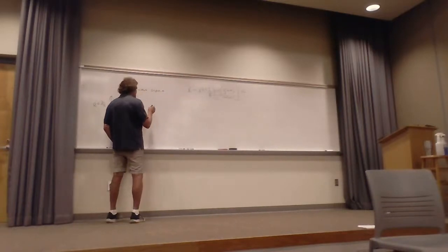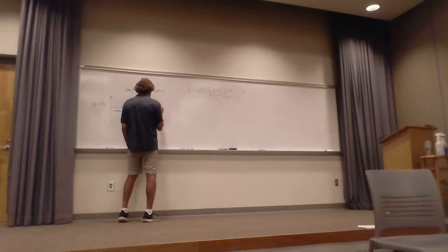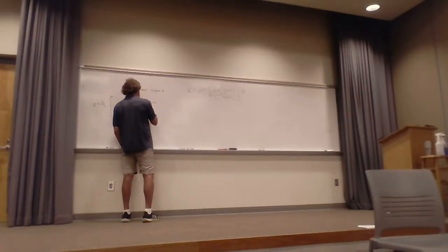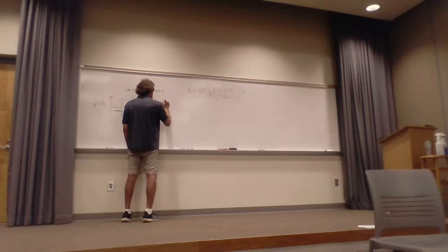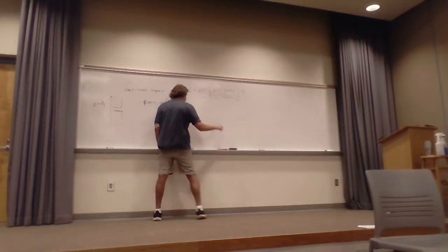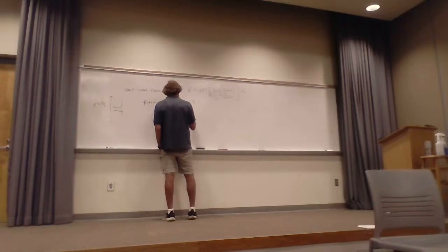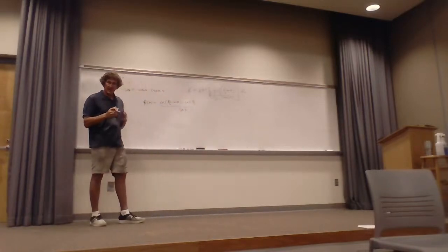Because remember, for the arbitrarily long dipole, you had an angular function, f of theta. It was really the square root I'm about to show you, but you had an angular function, I'll call it small f of theta, equal to cosine of beta L over 2 cosine theta minus the cosine of beta L over 2, divided by sine of theta. Do y'all remember? That was the entirety of that integral, right?